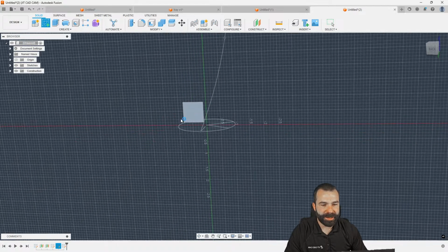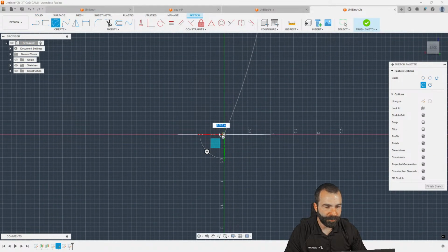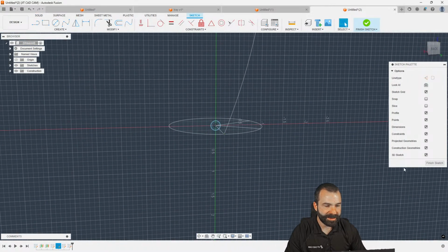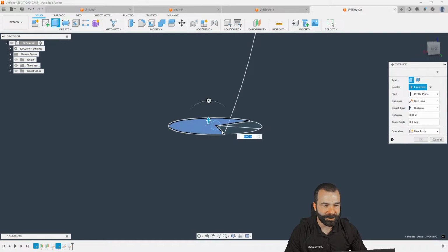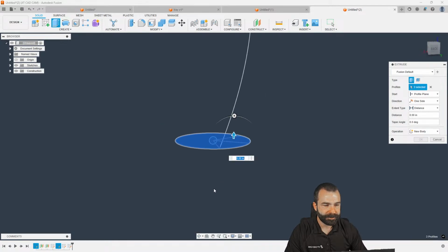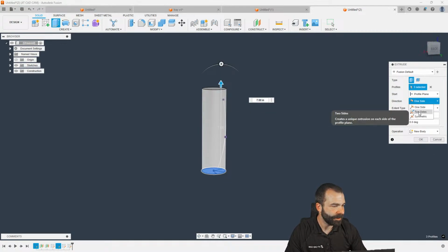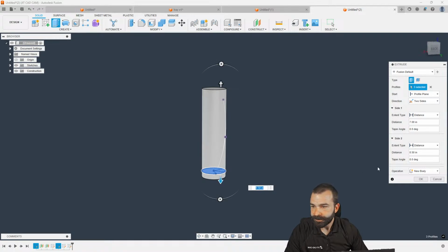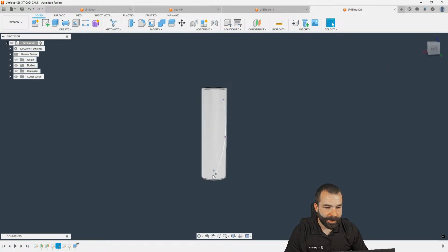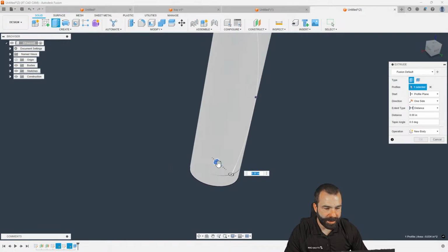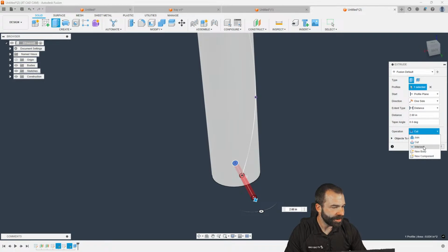So again, as we're going to create a sketch here now, hopefully I can cut this cylinder as we've talked about. We'll go a little past that. And actually, I'm going to say 2-sided here. And we're going to extrude our hole now. And let's just say this goes through all.